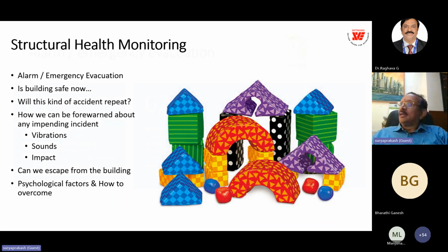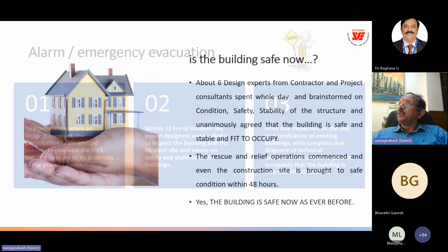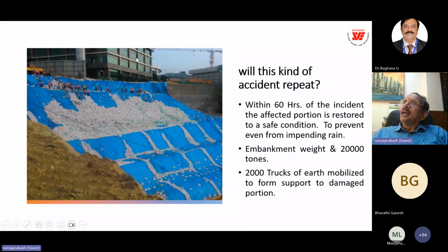So these are all very practical cases, where a presentation was made post-failure to the occupants of the building, and we could restart the activity by rehabilitating the deep excavation with conventional sandbags. We put 20,000 trucks of soil within 48 hours.